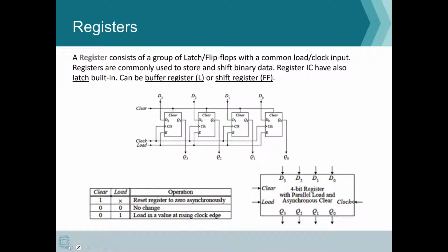So the load pretty much enables each individual flip-flop or latch, and then if it is made up of flip-flops, then the clock signal, whenever you have a rising edge or a falling edge depending on your flip-flop, will either load the value or change the value in each individual flip-flop, and all individual flip-flops will simultaneously change the value.